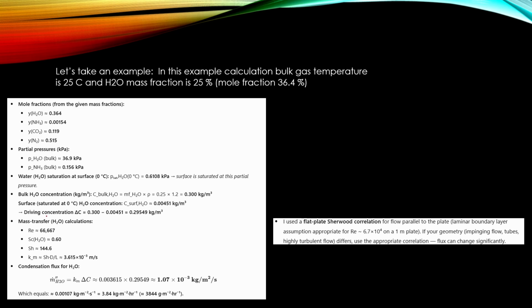And the so-called driving concentration is the difference between these two values. We need to also calculate the mass transfer coefficient, and that is a function of the Sherwood number and this diffusivity. And when we have these values available, we can calculate this condensation flux for water vapor.